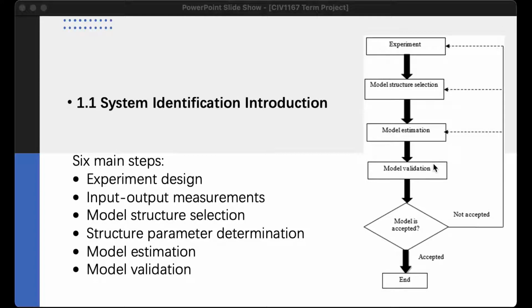3 types of model are common in system identification: the black box model, the gray box model, and the user-defined model. The black box model assumes that the system is unknown and all model parameters are adjustable without considering the physics background. It can adjust all the parameters arbitrarily.